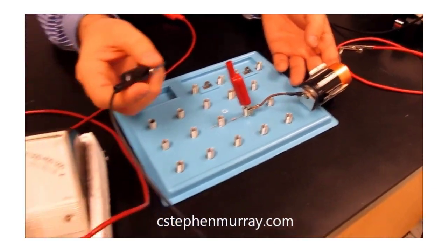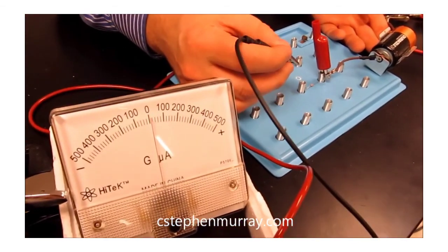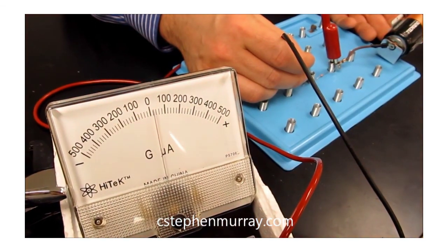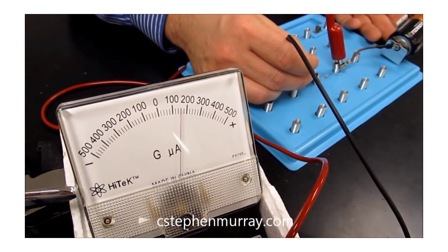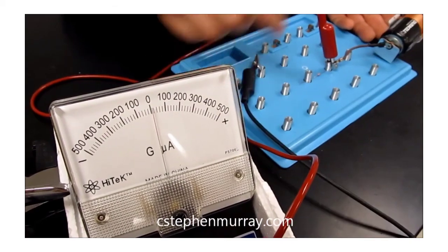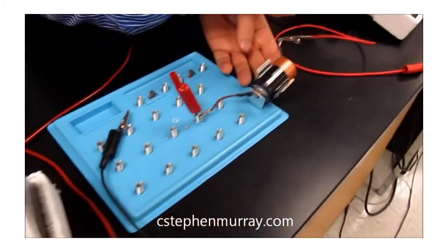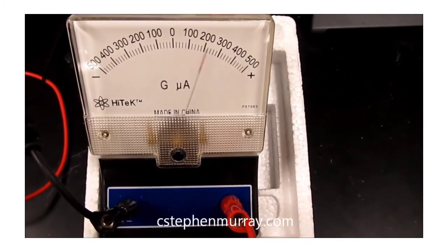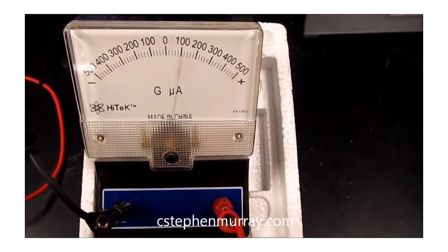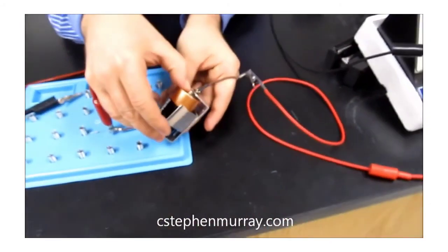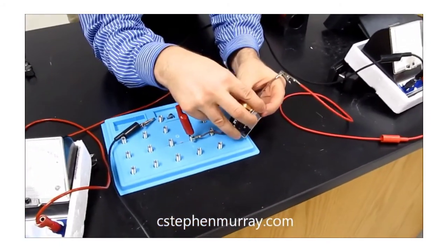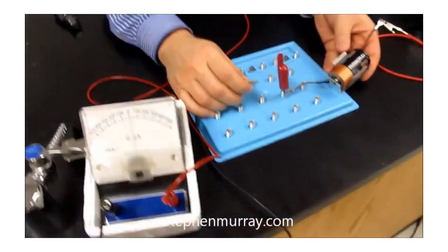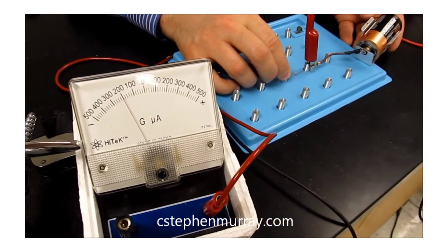So looking at the galvanometer, I'm going to connect the circuit, and if the positive current is flowing into the red, it reads positive. Again, looking over here at the circuit, the positive current flow is going into the red side of the galvanometer, and that's why it reads positive. Now let's switch the battery around so that the positive current flow is flowing into the negative. So watching the galvanometer, it reads negative.